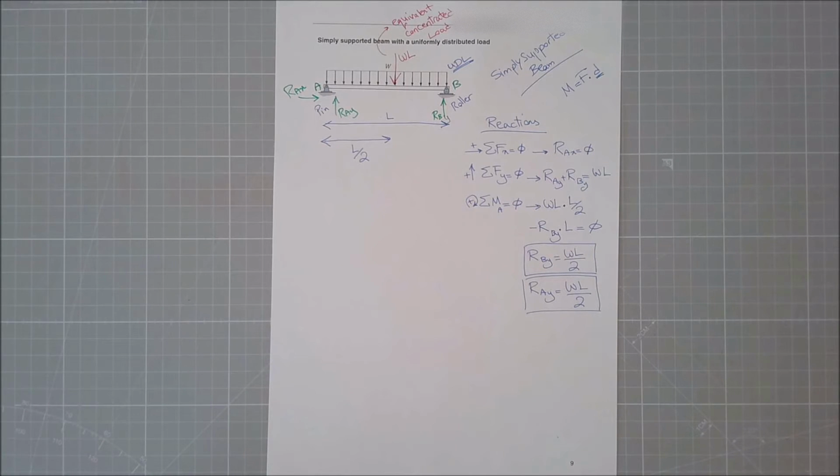Now, the methodology to figure out the bending moment and the shear diagram indicates that you start from the left side of the beam. You carry on until something changes. That something changes will be an external concentrated load applied, an external distributed load just starting, a moment applied, or a pin or a support suddenly appearing.